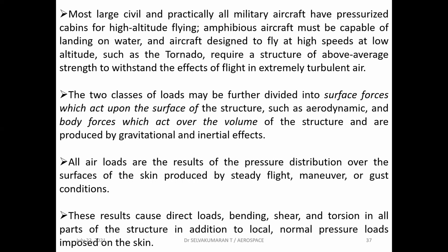The two classes of loads may be further subdivided into surface forces which act upon the surface of the structure, such as aerodynamic forces, and body forces which act over the volume of the structure and are produced by gravitational and inertial effects.